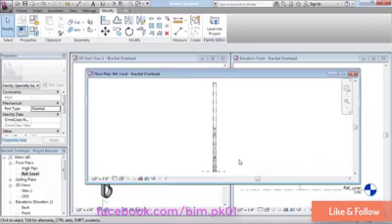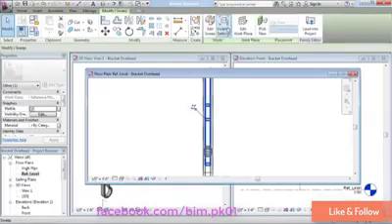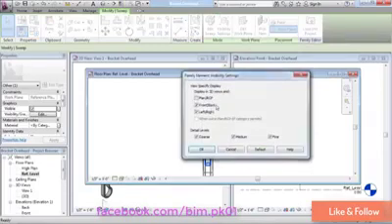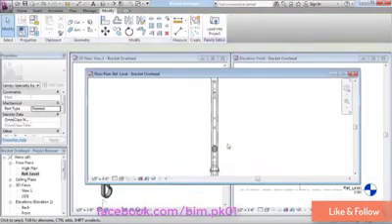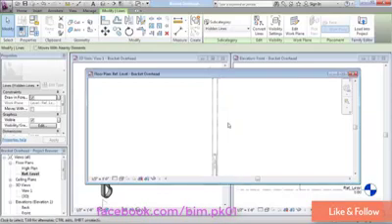In the previous movie, we talked about symbolic lines. And so what you can see here, if I open the floor plan in this family, is that all of the 3D geometry is grayed out. I have previously gone in and taken all of the 3D geometry and done the steps that we did in the last few movies to select it and edit the visibility settings and turn it off in plan. And that leaves just these symbolic lines here, and there's a short one at the end that display in plan view.